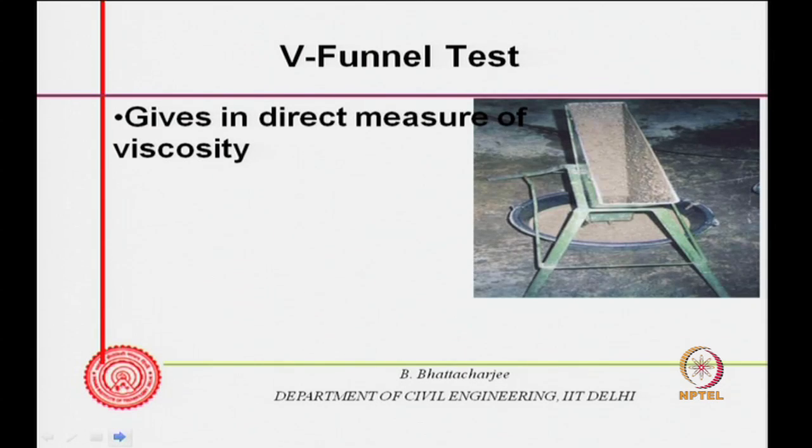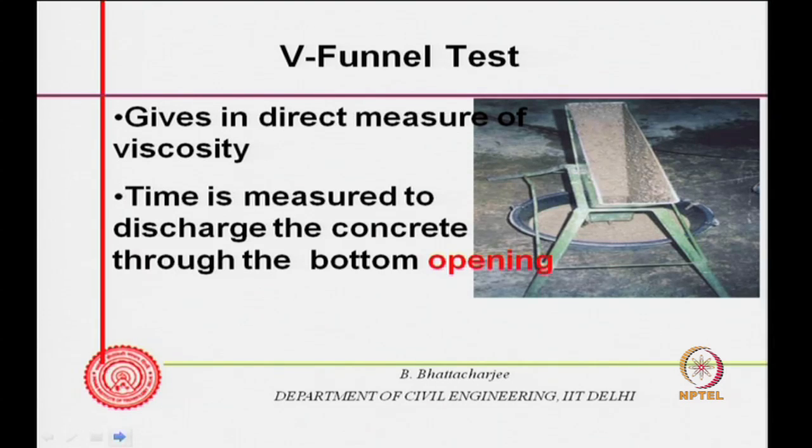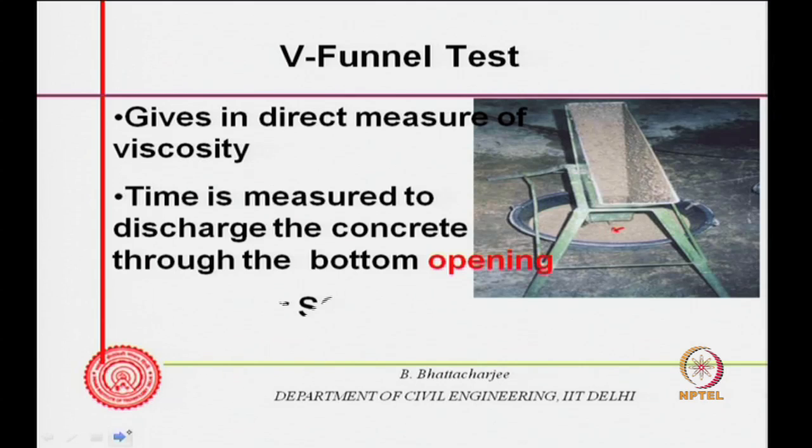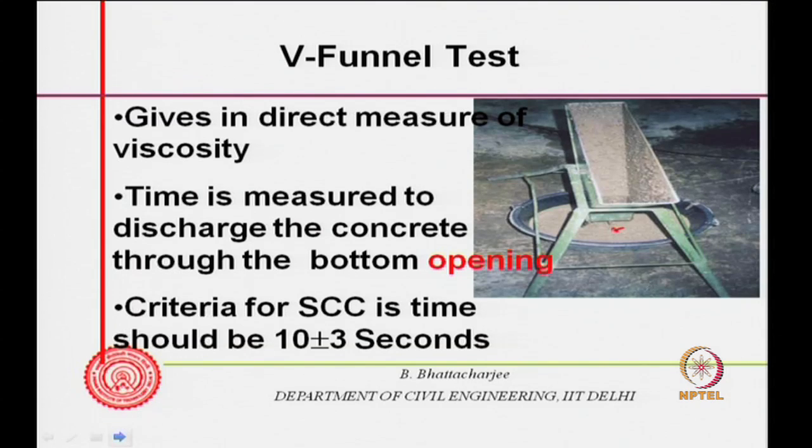that is what people felt, and you have a funnel which is closed at the bottom in the beginning, and you open the gate at the bottom. Fill it in a standard manner, then the time is measured for discharge of the concrete through the bottom opening, which is initially closed. If this time is 10 plus minus 3 seconds, then you can say it could be self compacting. So, basically you determine the fluidity, and this is a measure of viscosity.